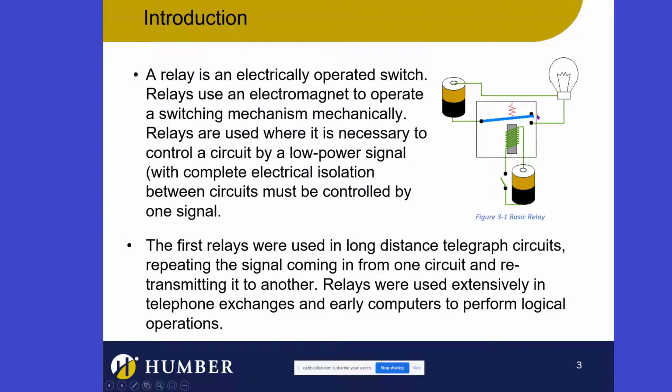And normally this is closed. So the spring creates the normal state. The active state happens when I energize this coil and I close this switch. So this is cool. Get this. I can use a switch that runs on maybe low voltage to control high voltage, and this may be like a 100-volt battery, and this could be a 100-volt bulb.